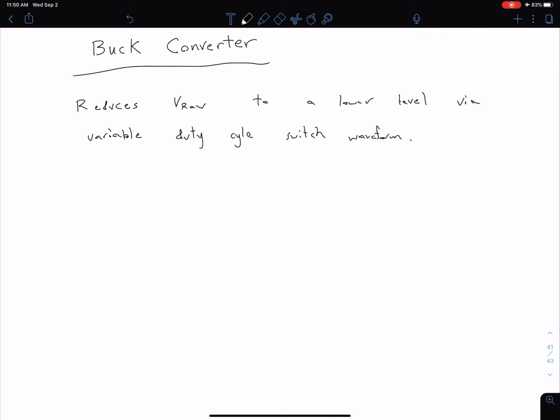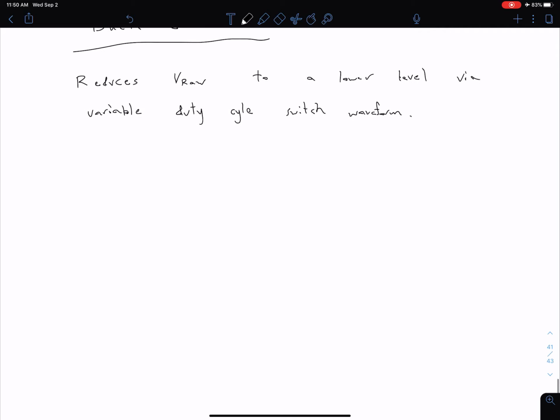Okay, so let's talk about a variable here before we look at our diagram or our circuit. For our buck converter, we're going to have this D buck, which is our duty cycle ratio for our buck converter. This is going to be defined as our on time for our switch over the period for our switching cycle. Again, this is our duty cycle ratio.